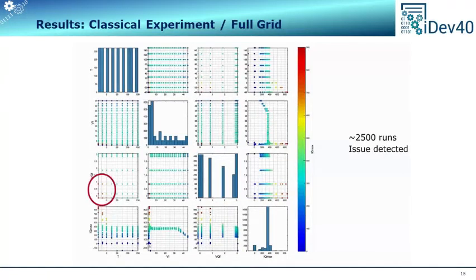Indeed, what we have observed is that first the behavior is for a very, very narrow range of input voltage, and it does not happen everywhere but only here. But then, with the help of this image, we can observe that yellow and red points, meaning that the requirements are not satisfied, are in this corner of forced output voltage and temperature, because for higher temperatures we only see green points. We can conclude that this is a very, very ugly case where the spec is violated in a very narrow region here, first in VI and then in the sub-region of temperature versus forced output voltage.